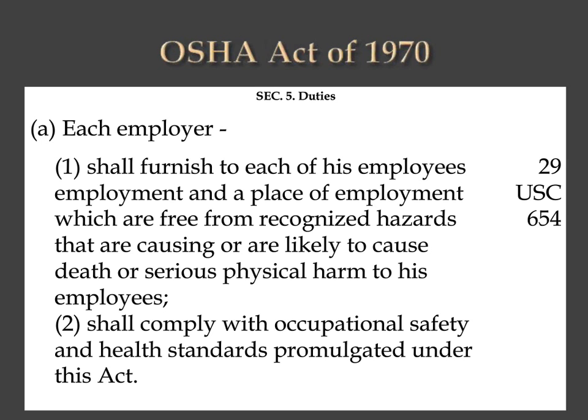So although you may have an employer who you work for, as an example, the general contractor also has duties and obligations to you, and those duties and obligations must be taken into consideration as well. Those rules can be found in OSHA under compliance documents, and they're under a 1999 document called CPL 2-0.124, which is multi-employer job sites. Obviously, if you're going to have multi-employers, you have to have multi-employers before the rule would apply.